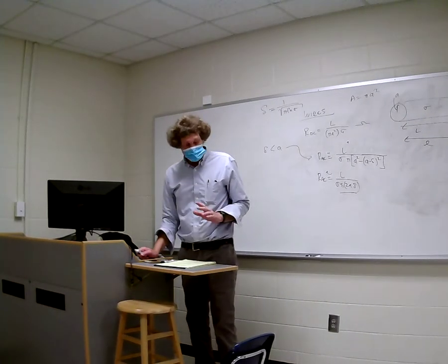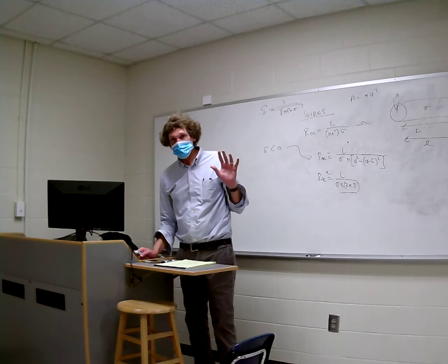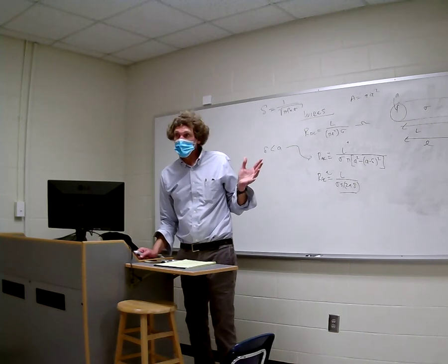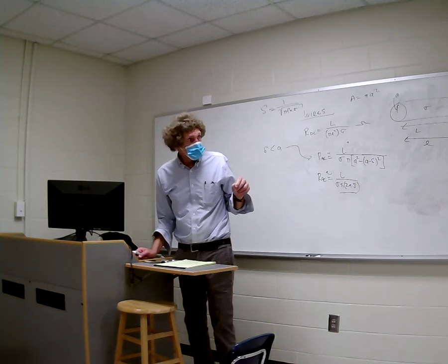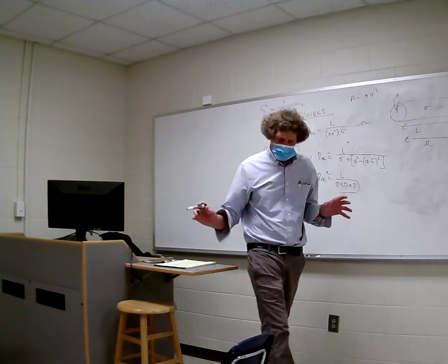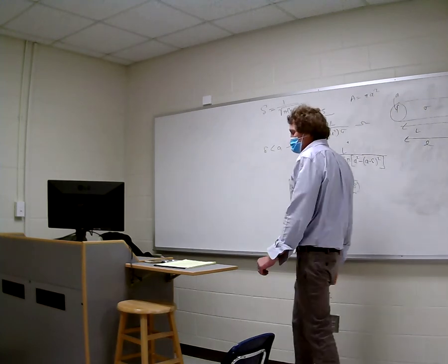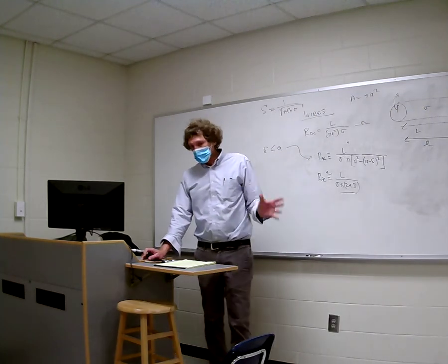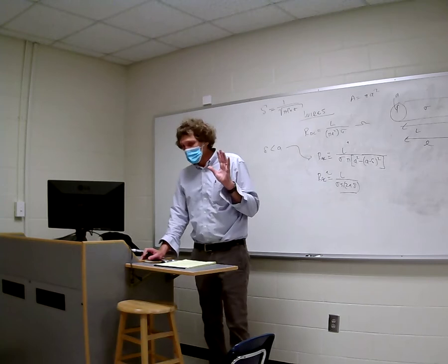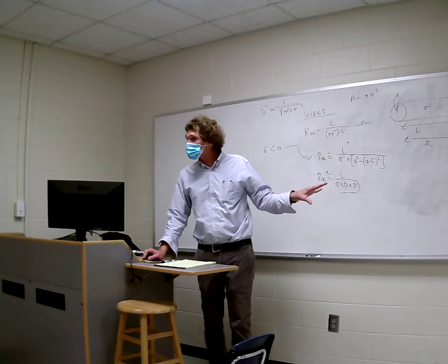So that's really the inductance external to the wire, and you'll notice it's not a function of frequency. It's only a function of what? The length, the radius, and the permeability. I'm sorry, this is external, it's assuming it's in air, I should say that. This 2 times 10 to the minus 7th comes out because mu is 4 pi times 10 to the minus 7th, and then it's divided by 2 pi, and you end up getting a 2 times 10 to the minus 7th out there. You don't have to worry about that. You all with me on this?